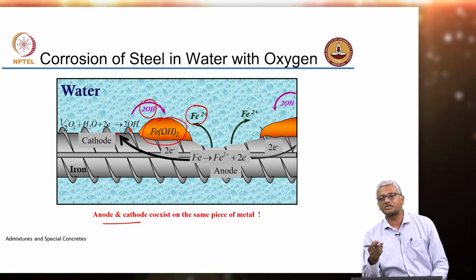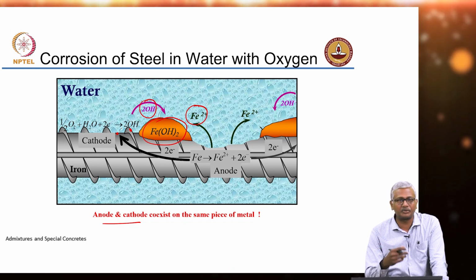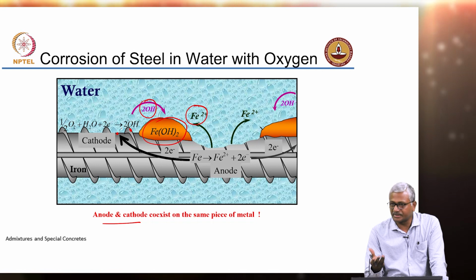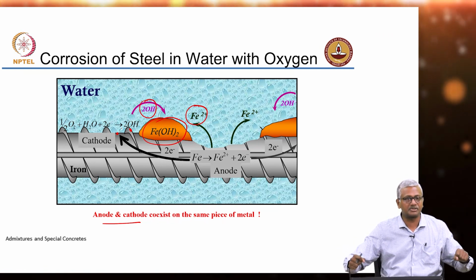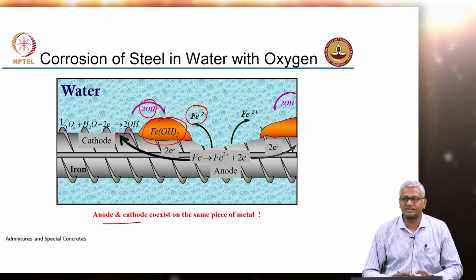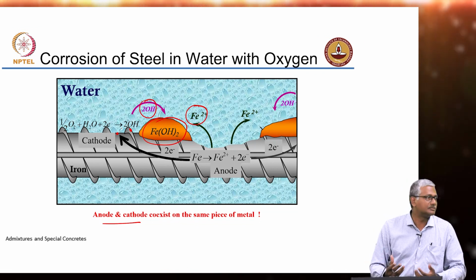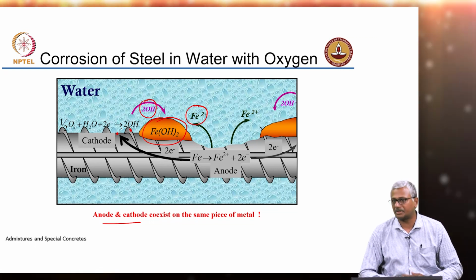Okay, if you look at the microstructure of steel, there are different phases present. Some are more liable to corrode as compared to the others. Now, in cold rolled steels or cold worked steels, you are doing cold working, no? You are twisting when the temperature is low. So, obviously, you are inducing some internal residual strains in the system. And those residual strains, if they are not distributed uniformly, you will definitely have some sites that act as anodic as compared to the others.